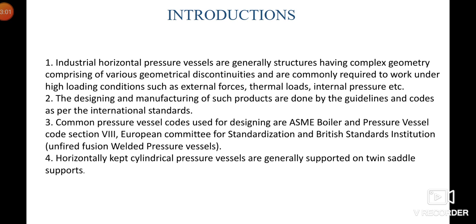Geometrical complexity, you will find that so many stress concentration points are also there that we need to consider, as given in the slide, comprising of various geometrical discontinuities and commonly required to work under high loading conditions like external forces, thermal loads, internal pressure. So the most important factor to consider in the design of the horizontal pressure vessel will be the thermal loads. Then after comes internal pressures and all other external forces also.